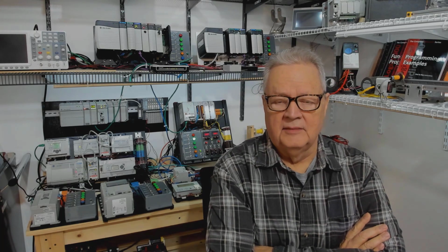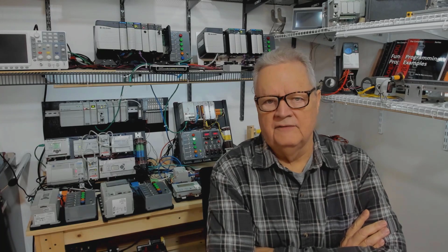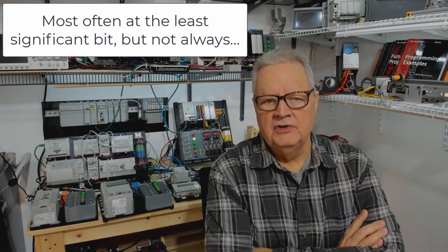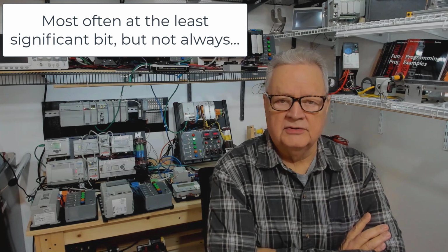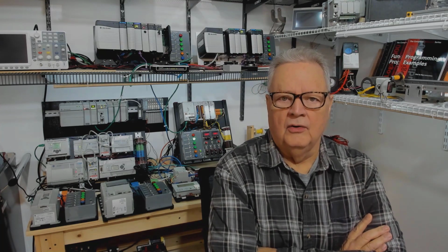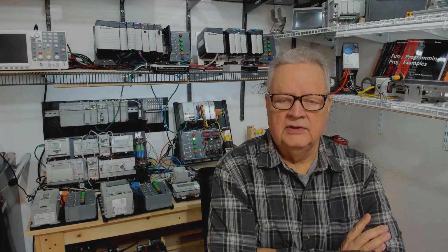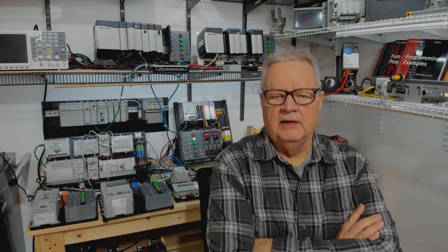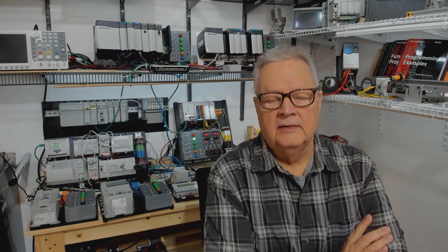didn't even get started with bit shift right, which is actually a little bit more complex. Because with bit shift left, you're always pushing the bit address value into bit 0, the least significant bit, and then you're shifting a length of bits to the left. And they unload when they leave the last position into the unload variable, whatever you named it. In our case, we named it output 0 so we could see a light come on when it unloaded a 1. Keep in mind, if it unloads a 0, it turns the light off.